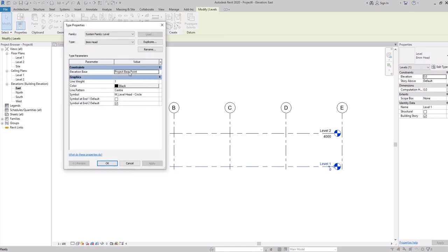You can edit the type itself. By clicking on it, you can change the base unit, the line weight if you want to change it, the type of line. Instead of center, you can go to dash, dash dot, or any other type that we have here. So for example, if I change it to dash and click on apply, you will see that it will change this way. If you want to go back, again, you can select the line and then click on apply. And this you can do as well for the grid lines.